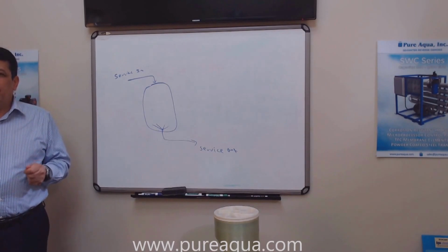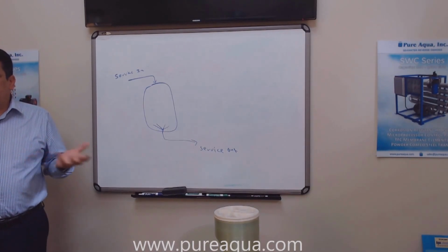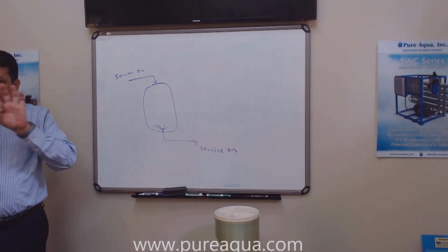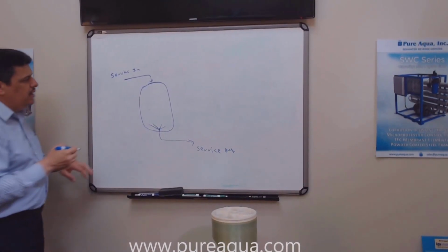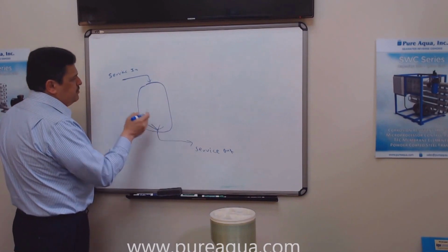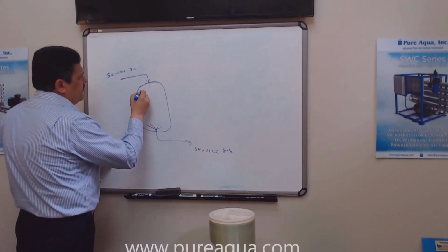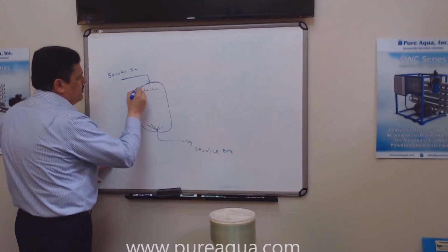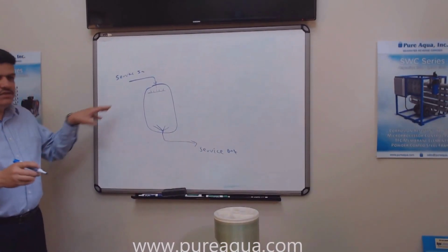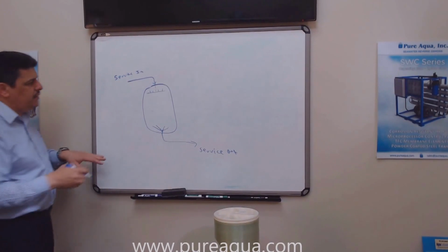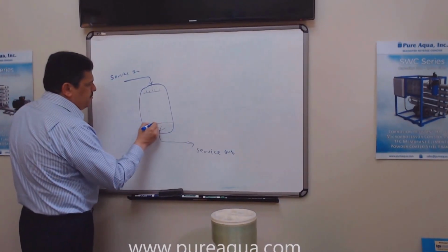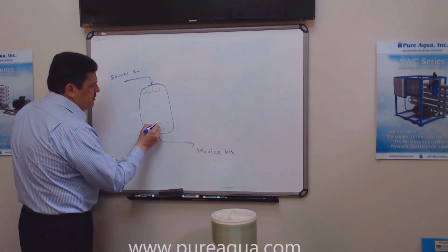Usually we call them either laterals, which are very fine pipes that have very small holes to prevent the sand from coming out, or the bottom distributor. And then here we have something called the upper distributor that distributes the water uniformly among all the surface area. Now at the bottom here, we have gravel.